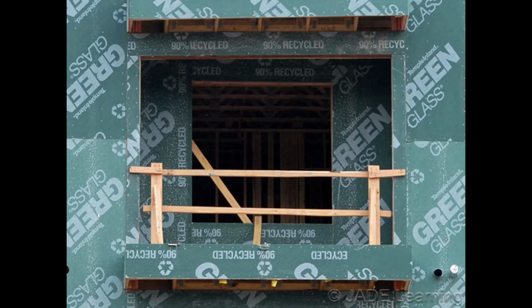Wall openings. Employees who are exposed to the hazard of falling out or through wall openings, including those with chutes attached, where the outside bottom edge of the wall opening is 6 feet or more above lower levels and the inside bottom edge of the wall opening is less than 39 inches above the walking/working surface, must be protected from falling. We protect our employees from falls through wall openings by the following methods. Number 1, guardrails or personal fall arrest systems.